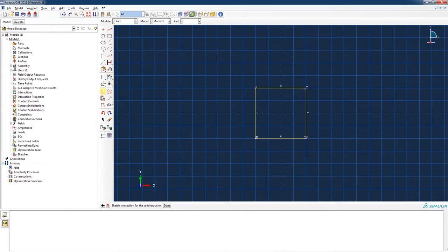If we come down here, there's some dimensioning tools. And let's see. Here's this one that says Auto Dimension. Select the entities to Auto Dimension. I'm going to just select all these lines. I'm going to hold down my Shift button as I select them so that they're all highlighted. And we hit Done, and it has these lines, and it shows that it's 20 millimeters by 20 millimeters.